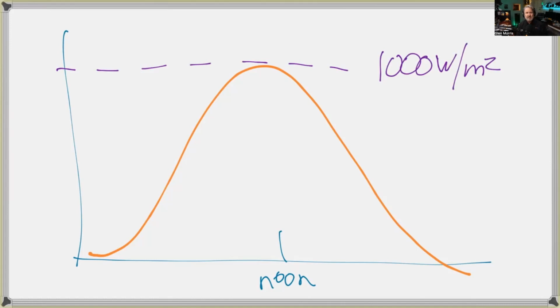You will measure under cloud edge effects. That's where you've got a lot of bright white cloud, but the sun's shining through unimpeded, and the clouds reflect lots of light. You'll get 1,200, maybe even 1,300 watts per square meter for a short period of time. And if you're on the edge of space, where there are no clouds, it's 1,352 watts per square meter, what's known as the solar constant. Ironically, it's not constant because it varies with how far we are from the sun by about 50 watts. But anyway, 1,350 watts per square meter is kind of the tops.